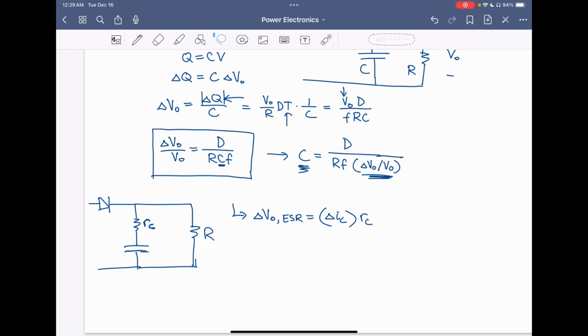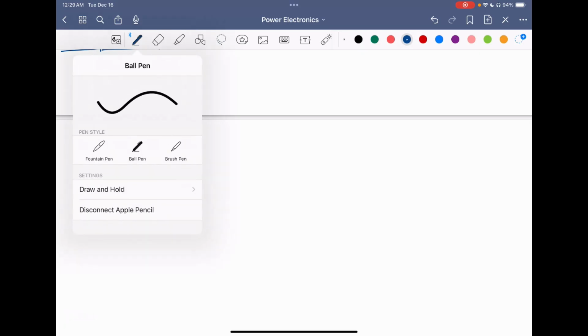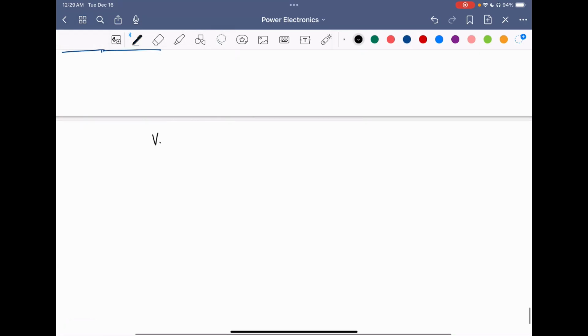In our basic analysis so far, we have assumed that components are ideal, and we get that the input power is equal to the output power, and we thus get 100% efficiency. From our analysis, we had found that the voltage conversion ratio, which is the output voltage over the source voltage, is equal to 1 over 1 minus d.